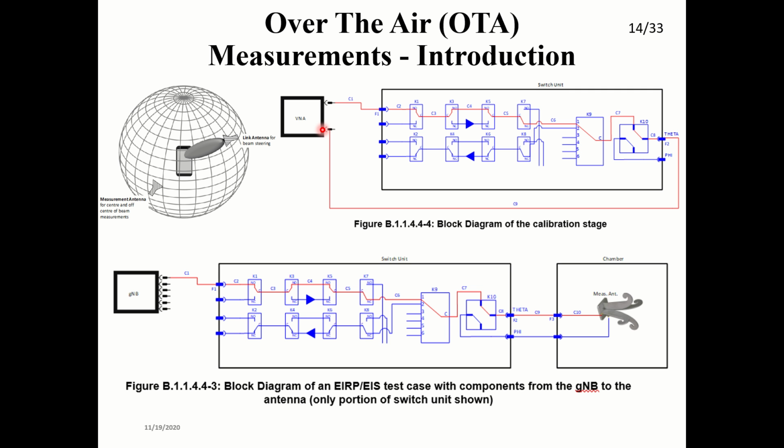So now what can you measure? S21. If you measure S21, then all the path losses that occur in this circuit can be found. Those things need to be compensated. Otherwise, what happens is, for example, you are straight away connecting your antenna and testing.